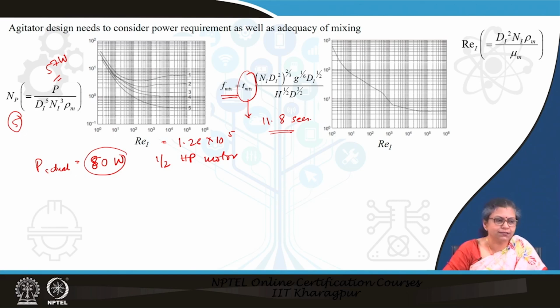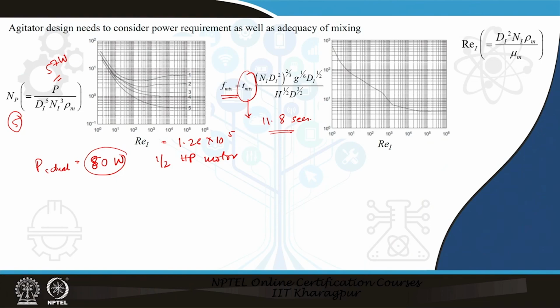So, this was just the simplest type of extractor, which is more or less a single stage contact. We have adopted a single stage contacting device because in this particular case the selectivity of water was very high. So, therefore, single stage was sufficient. For most cases we will find that a single stage will not be sufficient, we need multiple stages. Multiple stages can be provided by a number of mixer settlers in series, or more commonly by a continuous operation device, a packed column or a sieve tower.